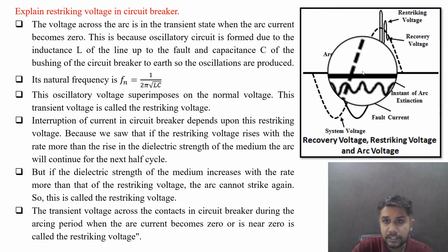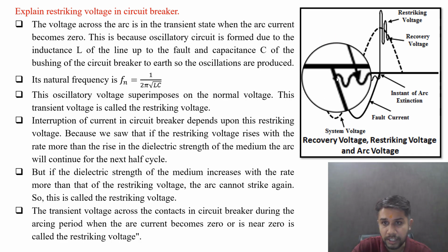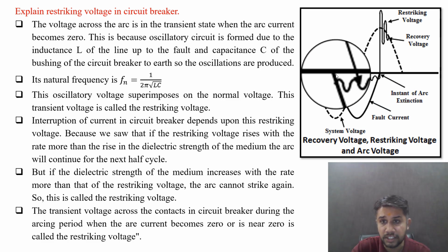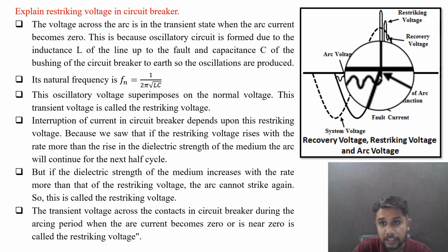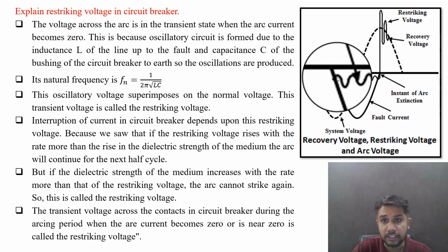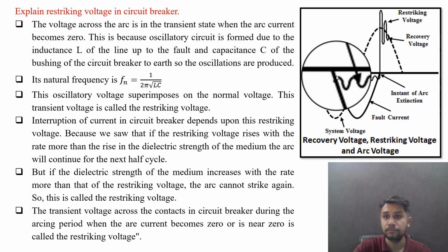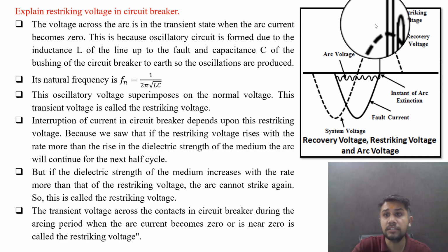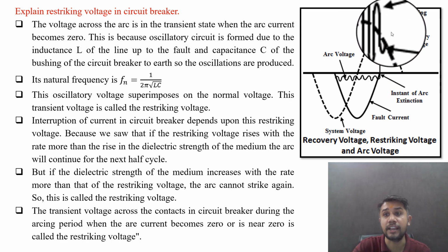You can visualize in this figure, this is the arc voltage, which is in phase with the fault current. Both are in the same phase because of the inductive nature. At the time when the current goes to zero, this is the voltage, that is the restriking voltage.